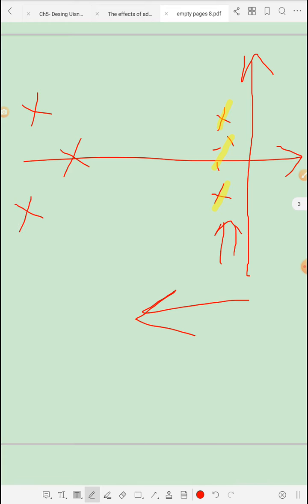The remaining poles should be far away from those dominant closed loop poles. So we have two categories of poles. Those are the dominant, and those are the far away, which are non-dominant. So we have dominant closed loop poles here, and we have non-dominant closed loop poles.